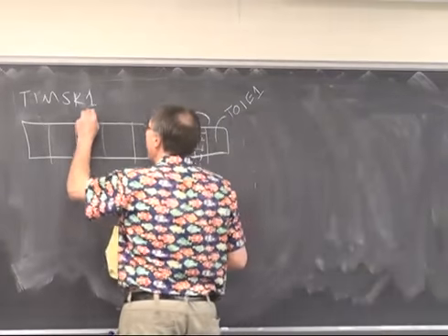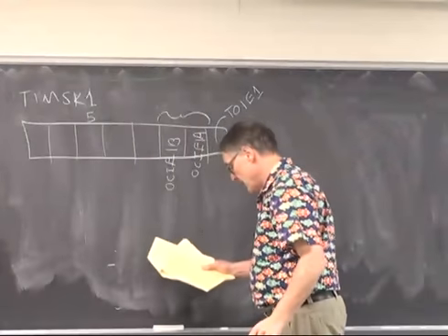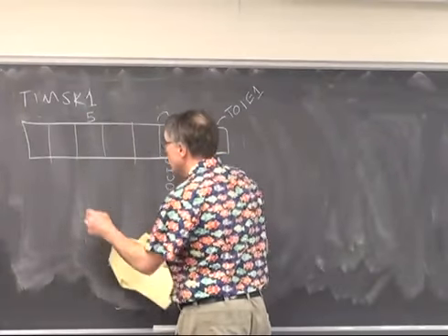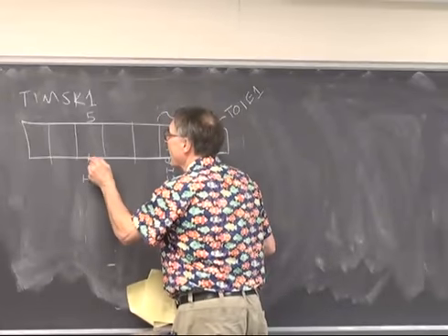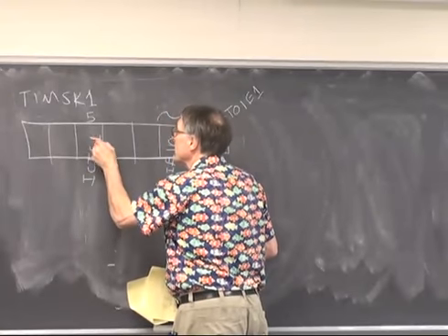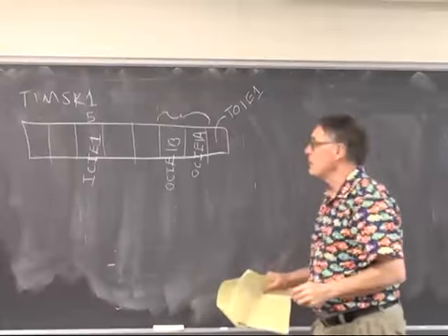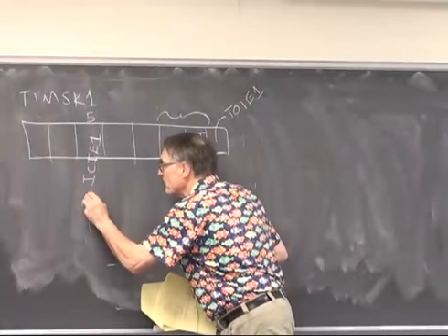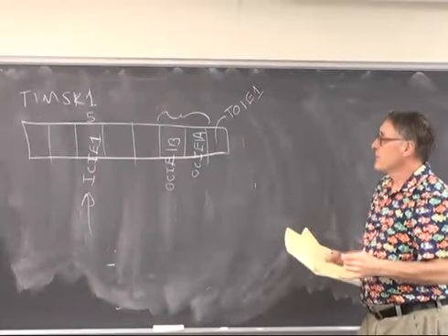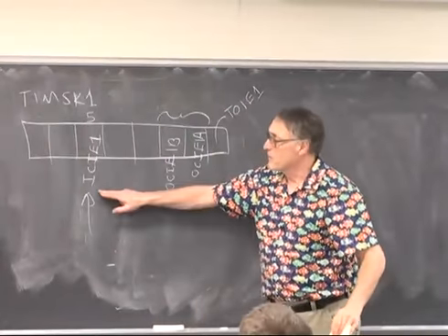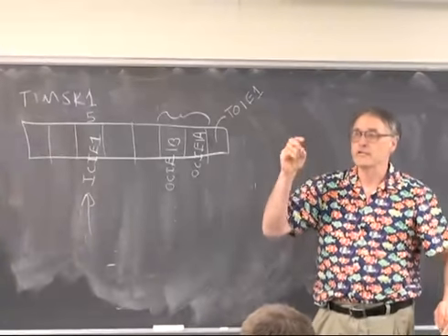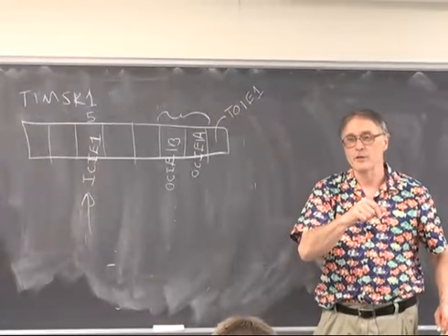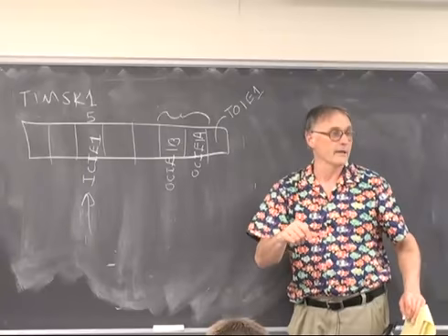And then bit 5 is ICIE1, the input capture interrupt enable. You're going to be very interested in that, because when this interrupt goes off, it tells you that an edge has been detected and there is a value in the input capture register worth looking at.